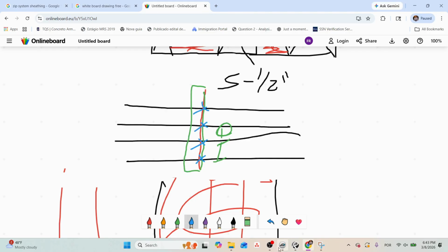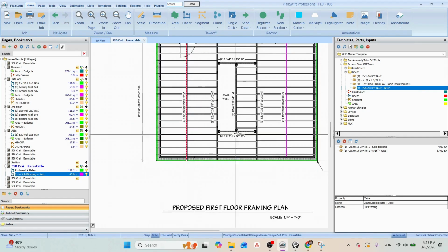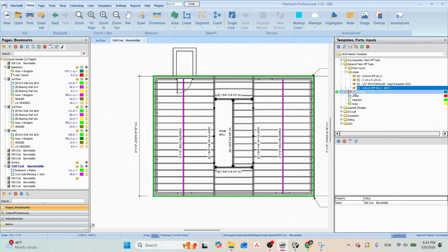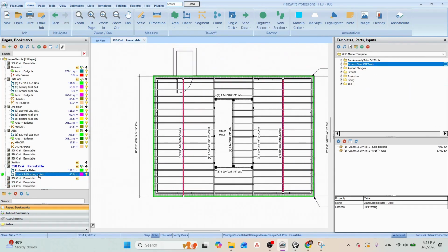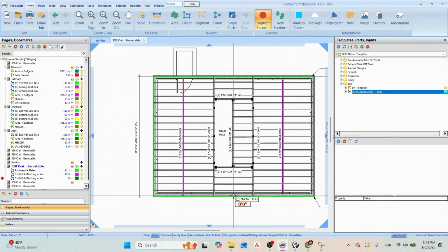That's exactly what we're doing in here. So in a 45 feet span, which is these two, at every 16, I account for one 2 by 10 by 14. Okay. Cool. I'll just put into auxiliary so we can create one for in here and here.